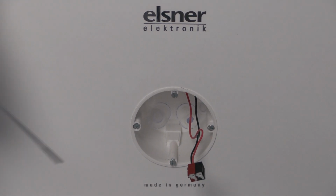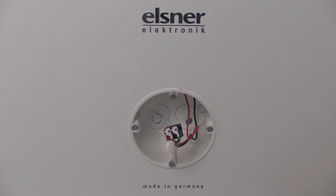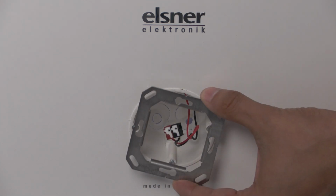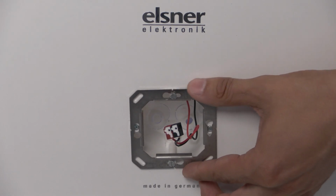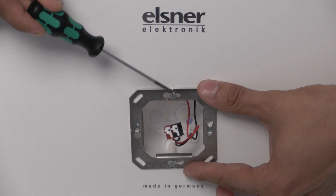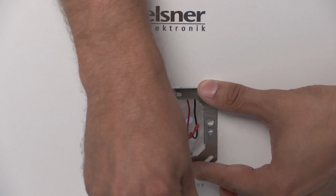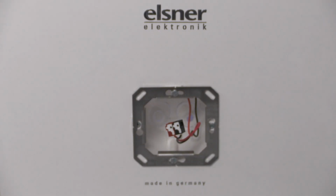So you see the open box in the wall. It's prepared with the KNX connection, and the first thing we have to do is to install this metal frame. I put the frame on the hole of the electrician box, then I insert it and I fix it with the 2 screws. You see the screw here and here. So you see the frame is installed, and you can rotate the frame a little bit over the long holes here, but for the demonstration it's okay.